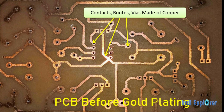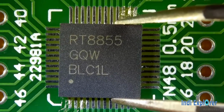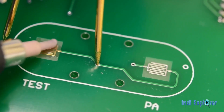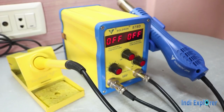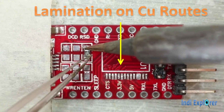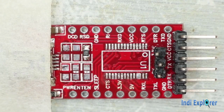This is like our houses, roads, and flyovers on the face of Earth. Contacts are locations where we place a component or connector. A contact has a gold or tin plating on copper to avoid oxidation before component placement. Soldering is a technique used to fix components on pads. The routes need no plating, so they are laminated by some insulating material. It protects the copper routes from getting oxidized and from scratches.